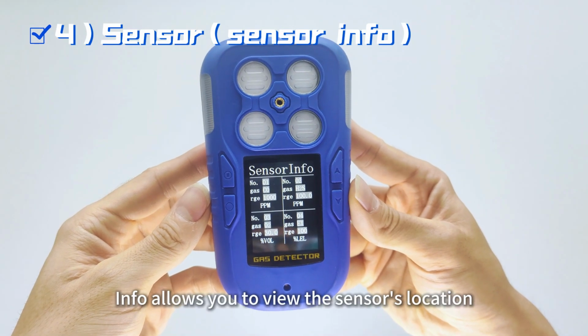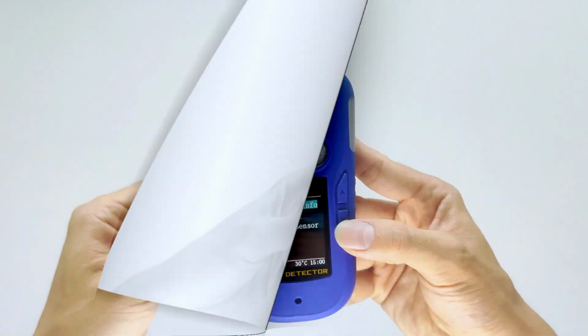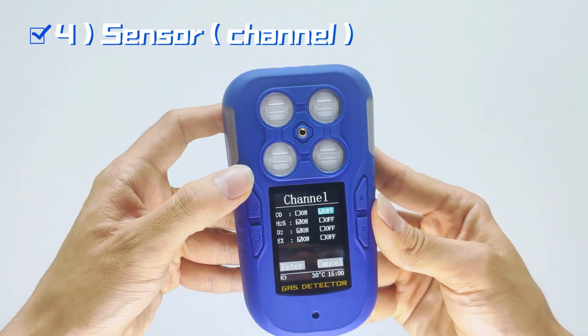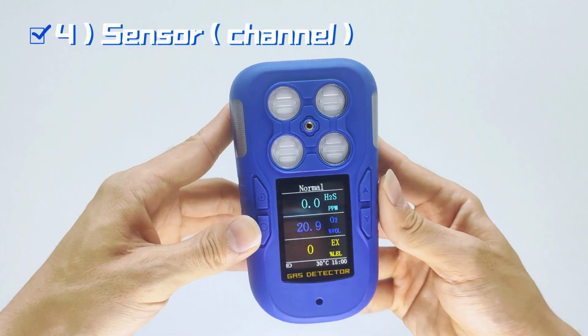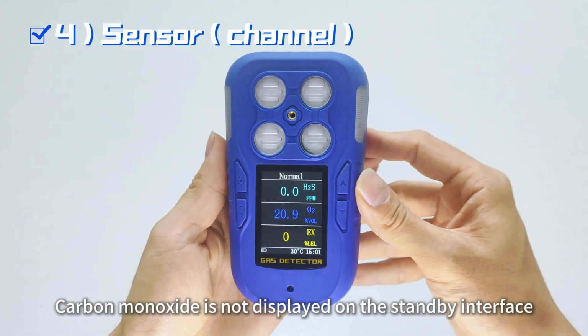Info allows you to view the sensor's location, gas type, measurement range, and unit. Channel is used to shield the sensor so that it does not display. For example, shield the carbon monoxide sensor. After shielding, carbon monoxide is not displayed on the standby interface.